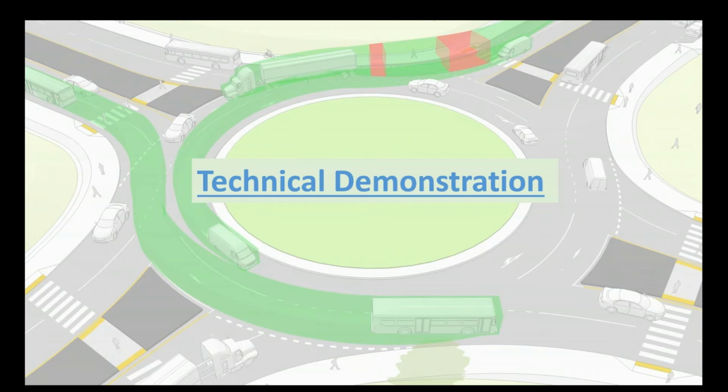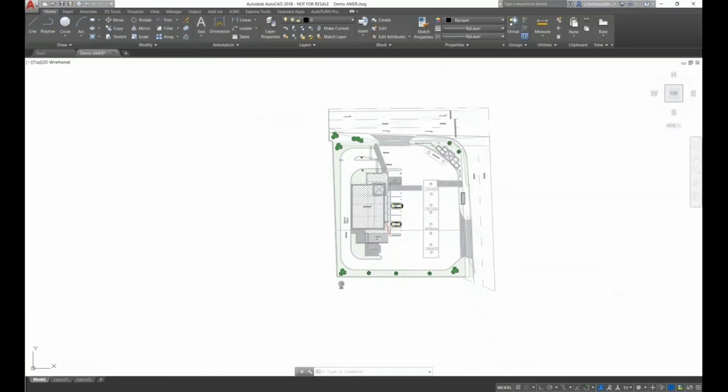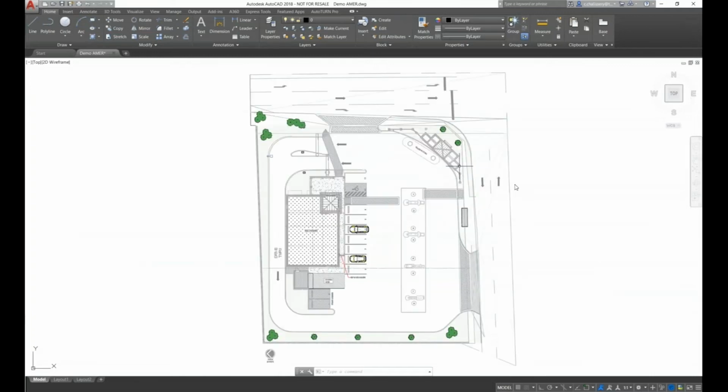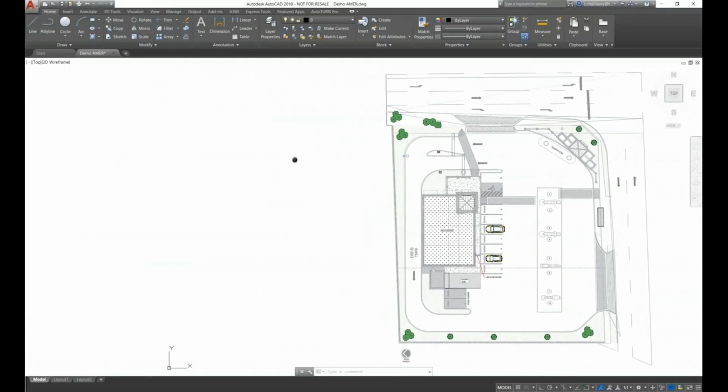So today we shall be analyzing a commercial gas station site plan with an adjacent fast food restaurant drive-through and the vehicles accessing the sites. So the foremost point in any swept path analysis is selecting the right vehicle. In this particular scenario, the vehicles entering the site will mainly access the gas station for filling the fuel, and the drive-through of the restaurant.